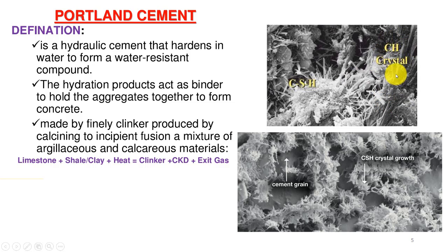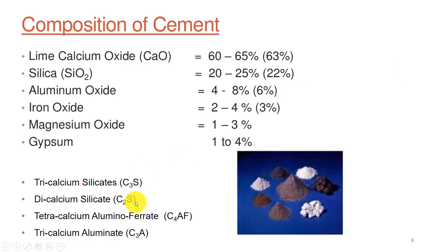These are the products of the hydration reaction. On the other hand, the hydration of the dicalcium silicate would involve at later ages. The microstructure formed by the dicalcium silicate would be similar to that of the former one, but it would at later ages. Moreover, it is hard to identify the hydration products of both calcium silicates. On the other hand, the hydration products of these can be easily distinguished based on their morphology and shape.